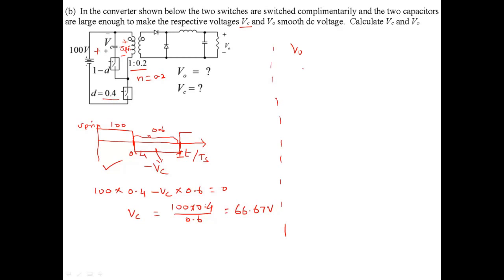So I will go ahead and draw the secondary voltage waveform, V secondary. That will be positive during that 0.4 Ts period, and a smaller magnitude negative for the remainder, 0.6. This is 0.4, that would be 1 T over Ts.